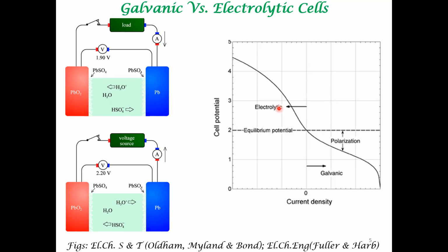When you impose, let's say, an external voltage of 1.6, you are generating hydrogen and oxygen at two electrodes. Water is split into hydrogen and oxygen. This is one of the purest ways of generating them. If you want to generate very pure hydrogen and very pure oxygen, you employ electrolysis. Water electrolysis is done extensively in the industry due to certain technical reasons. We will go into these reasons later in this course.